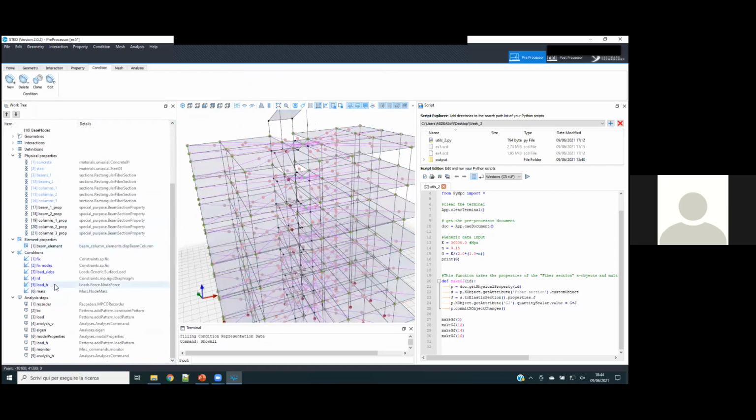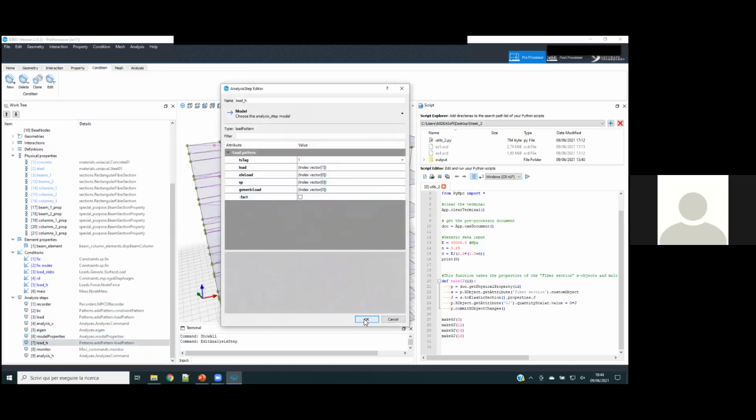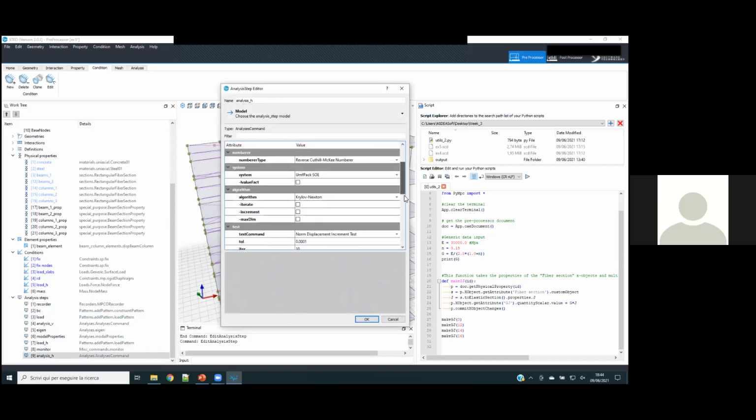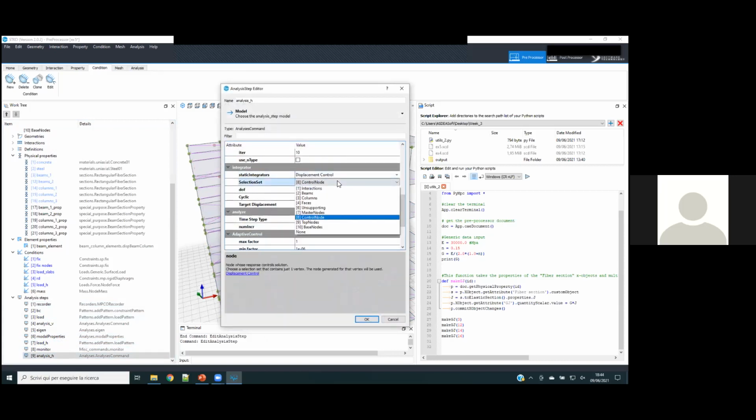So this force is there so that I can make a pushover analysis on this model. In fact, after all of these steps that we already talked about before, I add my horizontal load with the same time series that I have used for the vertical load, which I can reuse because I reset the pseudo time step. And then I define the horizontal analysis, which is a displacement control analysis with a specific control node, which is the top node, in the first direction, so in the x direction, with a target displacement of 1 meter, which is a lot. But it's just to show that the model will yield the pushover curve.